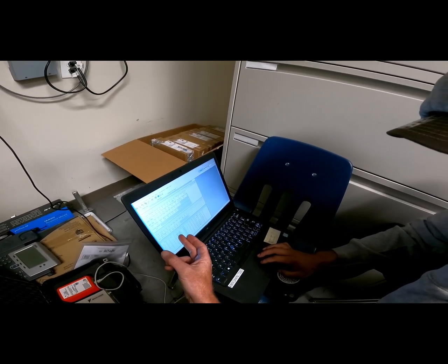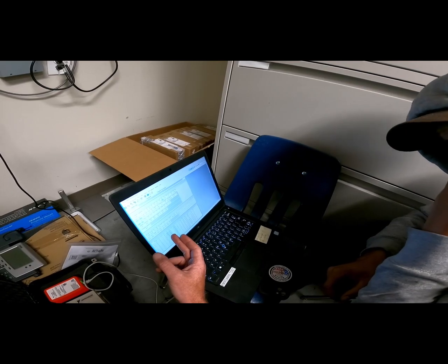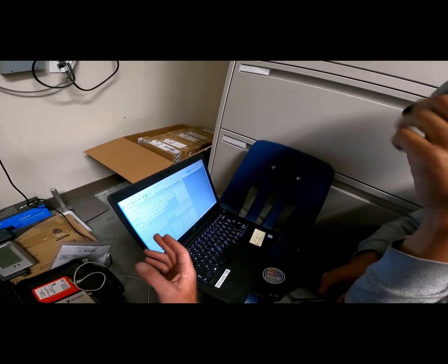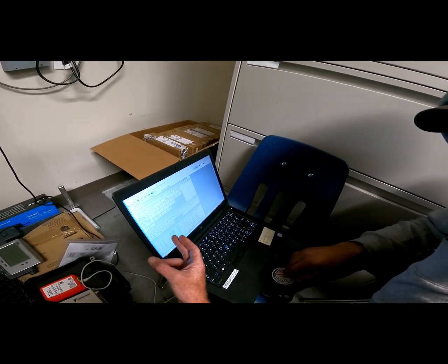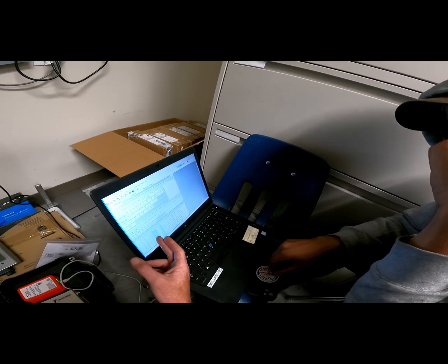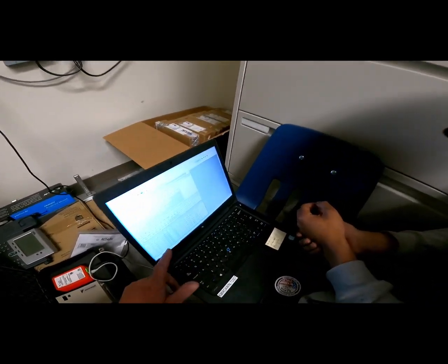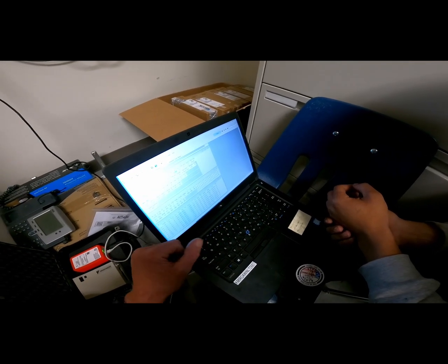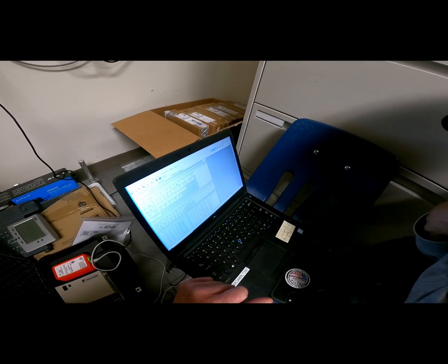Now, this liquid pipe temperature is not the temperature of a liquid pipe that you're used to seeing. Usually the liquid is what comes right out of the condenser, correct? This liquid pipe is after the metering device, before it has evaporated, so it's at saturation temperature. So you know that your refrigerant is evaporating in unit 21. It's evaporating at 58 degrees.